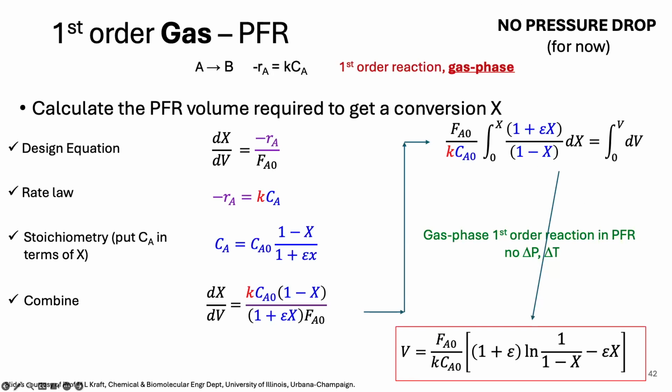So far we've been considering what happens when we have no temperature change, isothermal, and also no pressure change. Whereas we may be good at keeping temperature constant through heat transfer, heat exchangers, and such, it can be difficult, especially in a tubular reactor, to avoid pressure changes. So let's see what effect that has, how we can account for that, and where that's important.